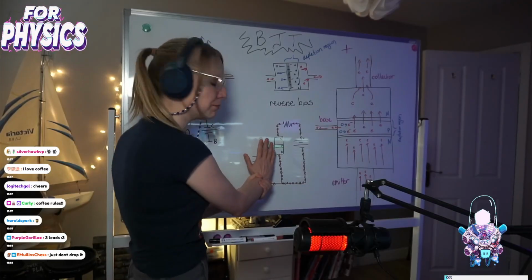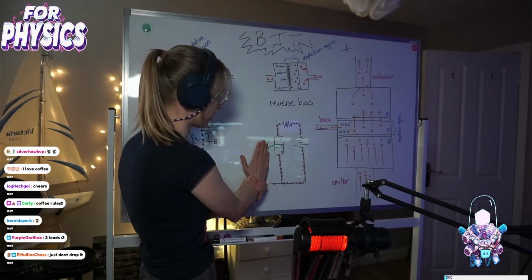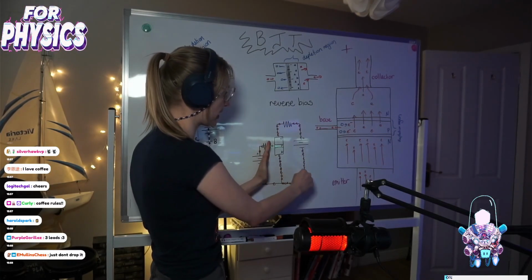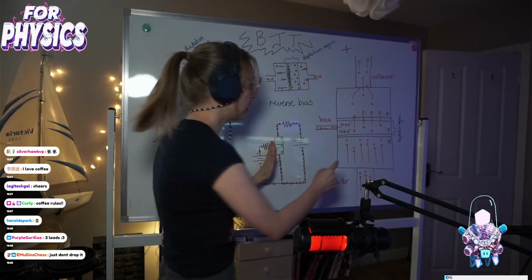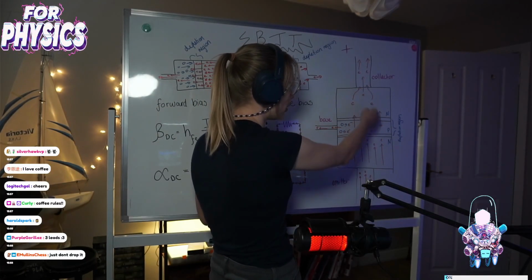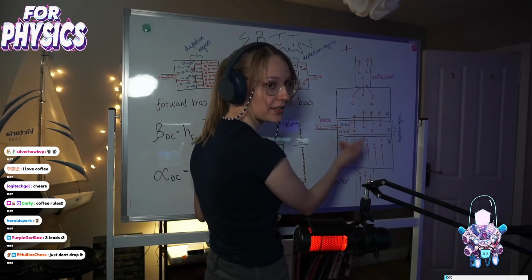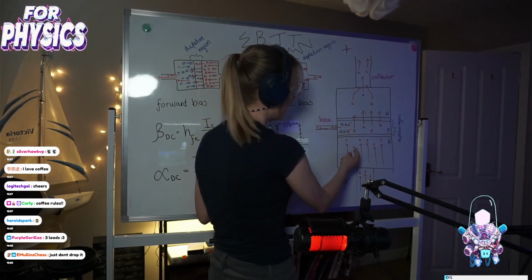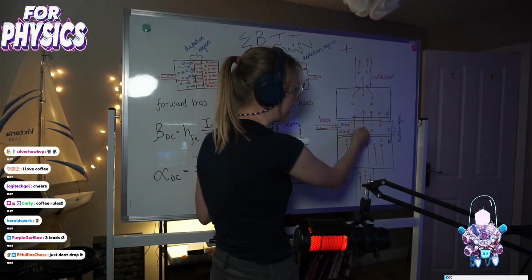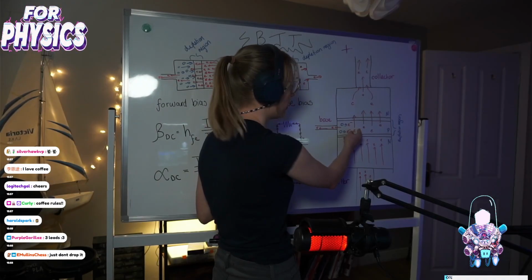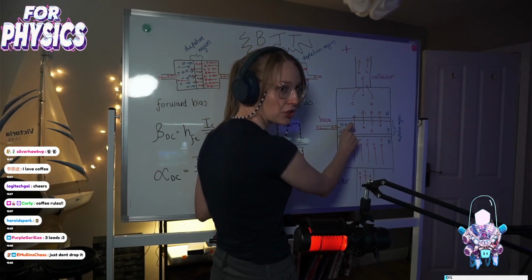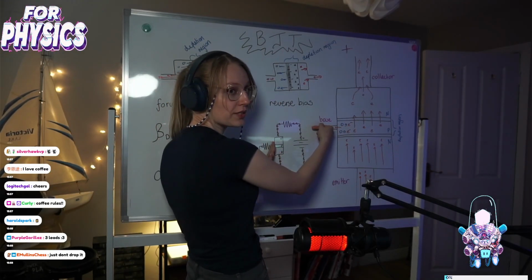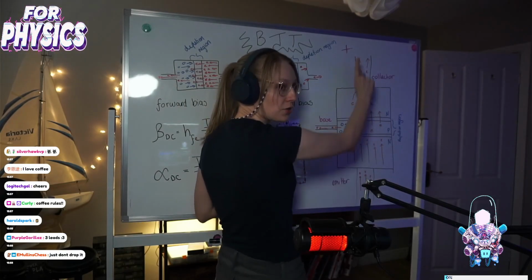So let's say I removed this part of the circuit. This doesn't exist. And I just put on a voltage of 5 volts. This is the only circuit we're looking at. The electrons will not flow, because there isn't enough energy to get them across this barrier. The only reason electrons can flow to the collector in the first place is because the electrons can get into the P region, because of this electron-hole pair annihilation that's happening here. Then the valence electrons go into the base, while the free electrons get to go to the collector.